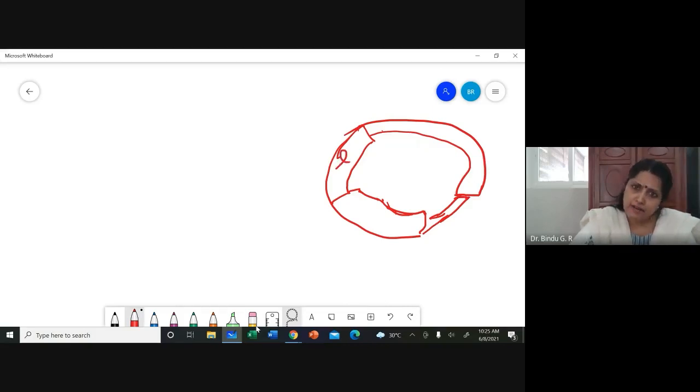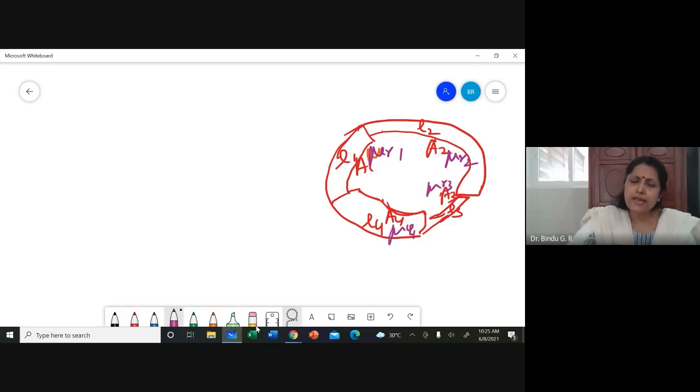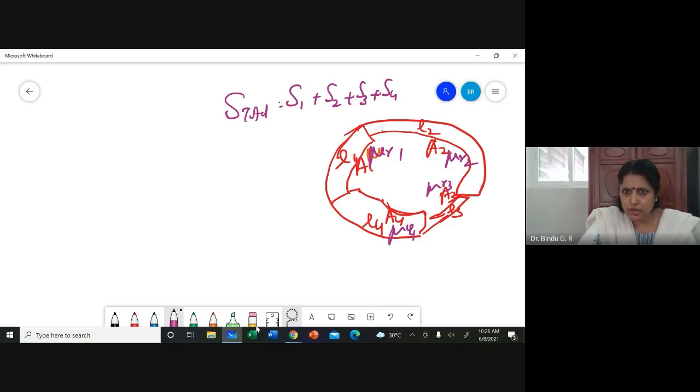So you can have L1, L2, L3, L4, and A1, A2, A3, A4, and this will have some mu r1, mu r2, mu r3, mu r4. In any case, the total reluctance will be S1 plus S2 plus S3 plus S4. If at all you have an air gap here, Lg, so S g. And finally, the total thing is the same.